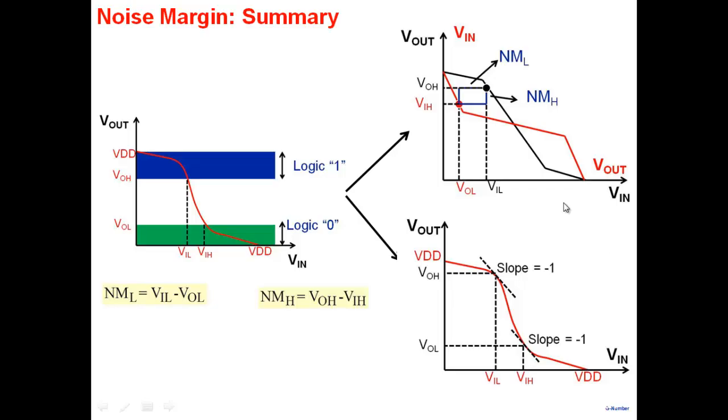Now, what I'm saying is that this is the most general one, and then you can use this, but we'll just see an example. I can always construct a VTC where you may not have a slope of -1, or the slope of -1 may not be a single point, but maybe a larger region. Whether those VTCs can actually be constructed or not, that's a different matter.